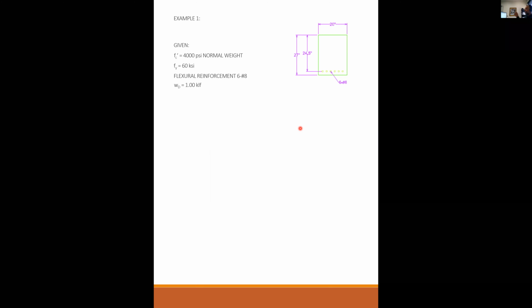And then you multiply times 150 pounds per cubic foot, and that gives you pounds per lineal foot. So it's not terribly difficult to get the self-weight, but I don't think I'm going to be asking for anything where you just use the self-weight and you do not use all the other dead load.